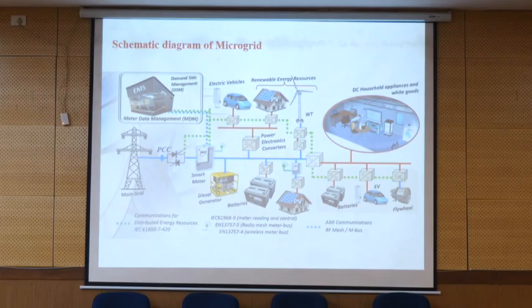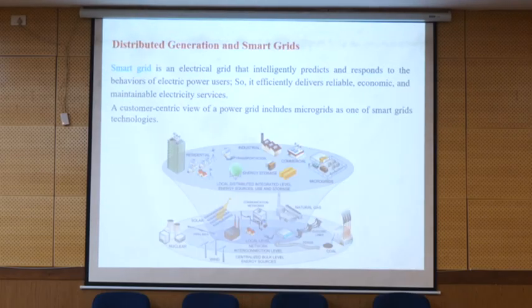Okay, so by this, when we return back to the grid connected mode, again it works like a current source and provide actually power to this bus. And if you have extra power, we can also consider for the grid. But the difference is that in grid forming, we don't need to have the PLL. But in grid supporting, we need to have PLL. Yeah, this is the difference between these two technologies when they are working in isolated mode.